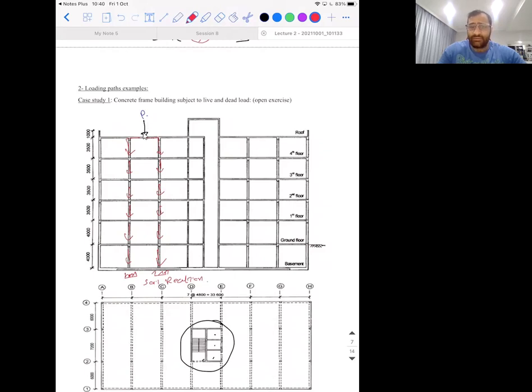What happens is half of it will go here, assuming the load is acting at the center, and the other half will go to the other side. They travel through the columns floor per floor until they reach the foundation. And for this building, for the geotechnical freaks, the foundation type is a basement foundation.